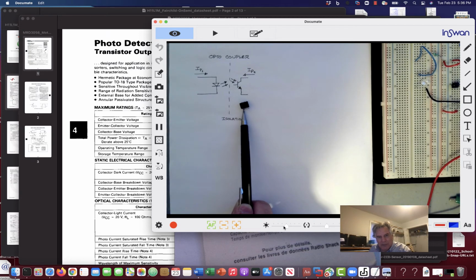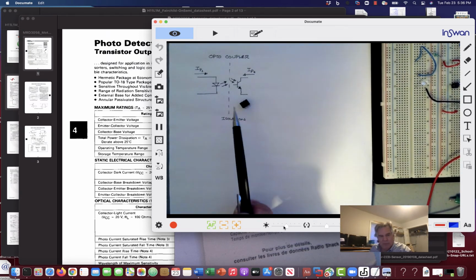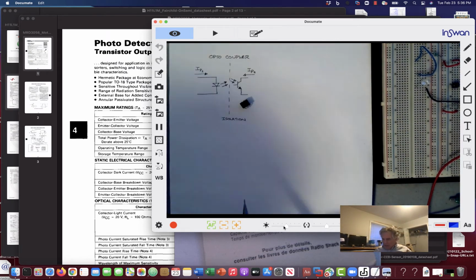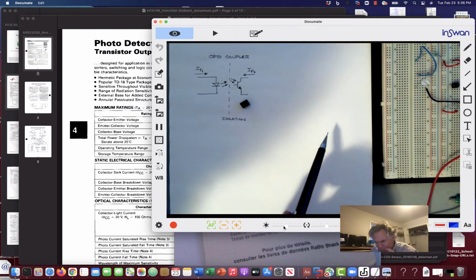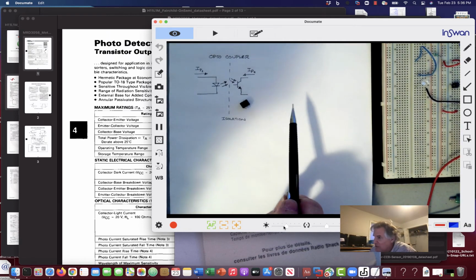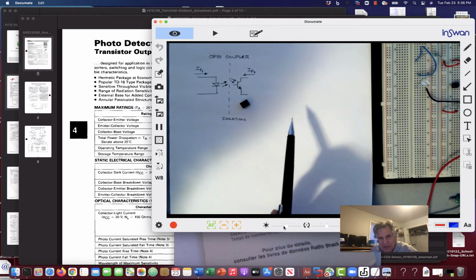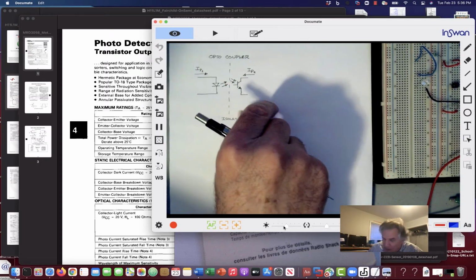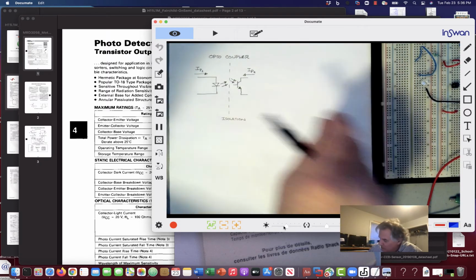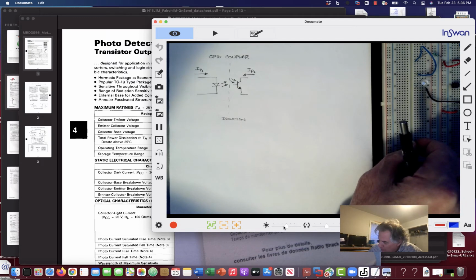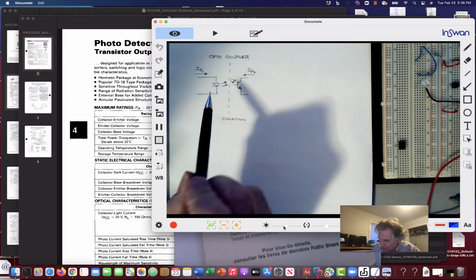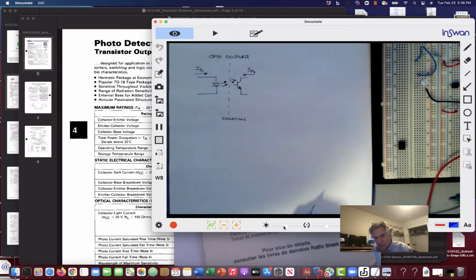Of course, now they would probably be a 6-pin dual inline package, or more often a 6-pin SOIC, SOT23-6 or MSOP of some kind. So, surface mount, but they still make these through-hole units. This is the basic operation of an optocoupler.